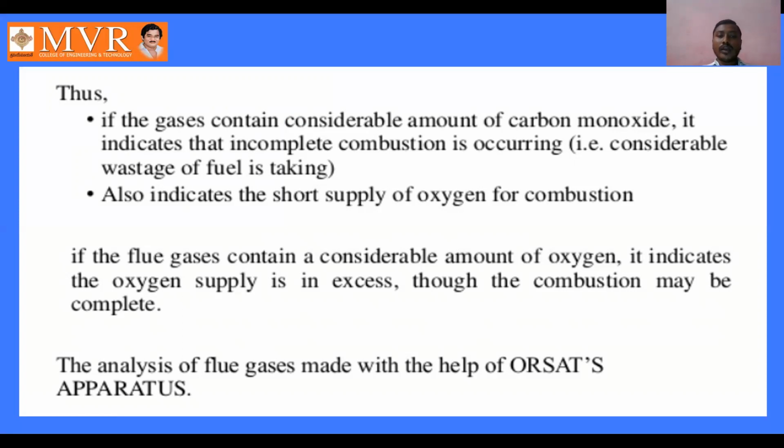So if the flue gases contain a considerable amount of oxygen, it indicates the oxygen supply is in excess. It means we are giving more oxygen for the combustion process, even though the combustion may be complete. After completing the combustion also, if we give more oxygen for the combustion process,